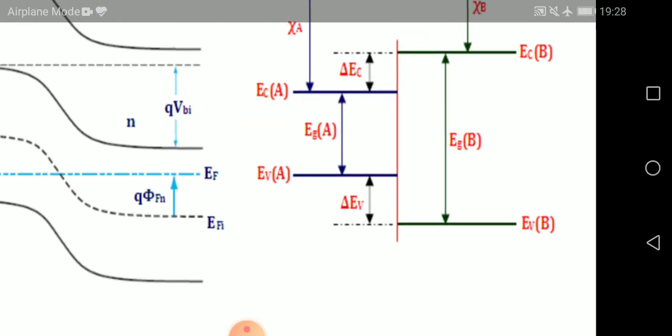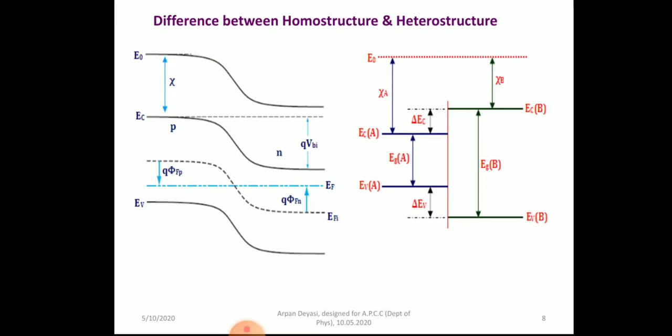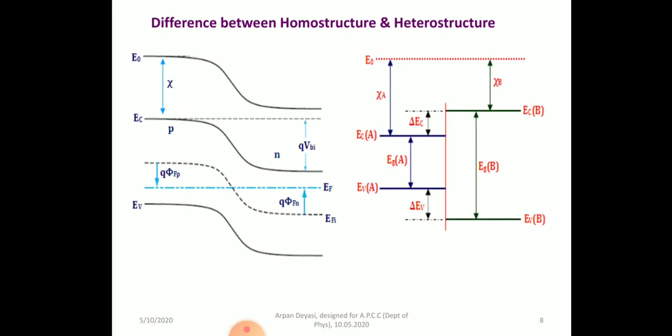So I am coming out exactly the same format as shown below. Again, you have a difference in the valence band, which will be called valence band discontinuity. Why does it come? Now look, there is a difference of the band gap, say EGB minus EGA.